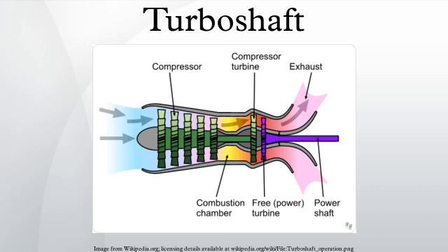Depending on the design, the engine accessories may be driven either by the gas generator or by the power section. In most designs, the gas generator and power section are mechanically separate so they can each rotate at different speeds appropriate for the conditions, referred to as a free power turbine. A free power turbine can be an extremely useful design feature for vehicles, as it allows the design to forego the weight and cost of complex multiple ratio transmissions and clutches.